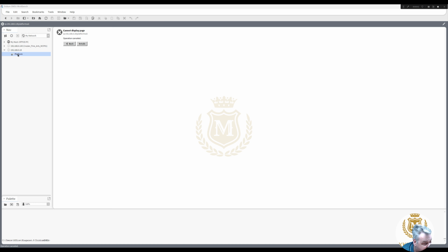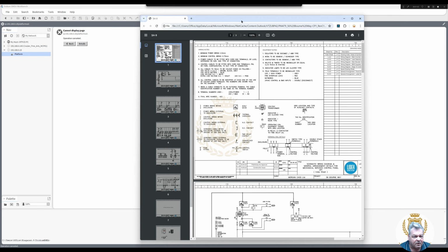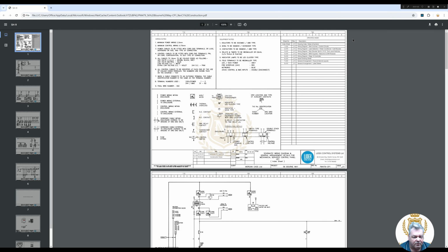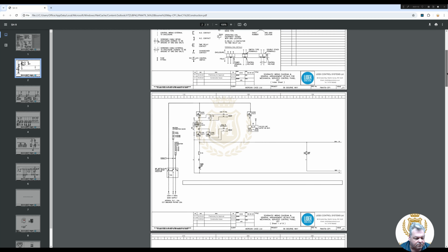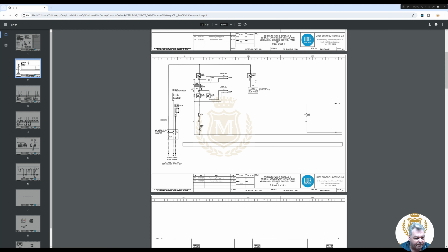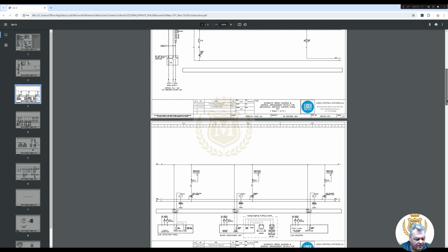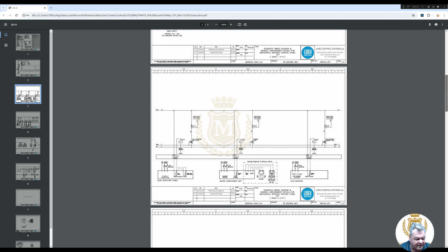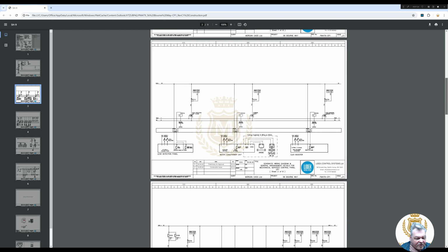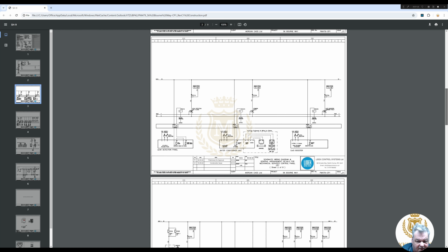Now, the Edge 10 can be used for Fancoil units, or it can just be used as a small controller. In this case, that's what we're using it for. So let's just bring across the panel drawings. So we've got our power supply, 24 volts there, we've got a socket in the panel, and that's got a leak detection panel, a water conditioning unit, a booster set.